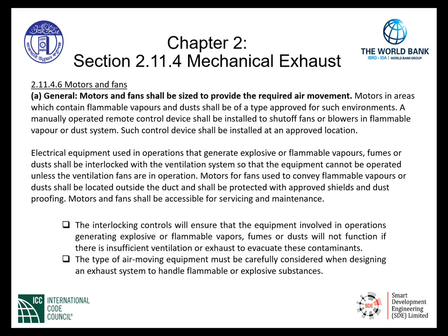A manually operated remote control device shall be installed to shut off fans or blowers in flammable vapor or dust systems. Such control device shall be installed at an approved location. Now, the electrical equipment used in these operations that generate explosive or flammable vapors, fumes, or dust shall be interlocked with the ventilation system, so that the equipment cannot be operated unless the ventilation fans are in operation.